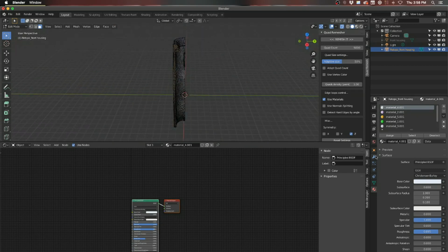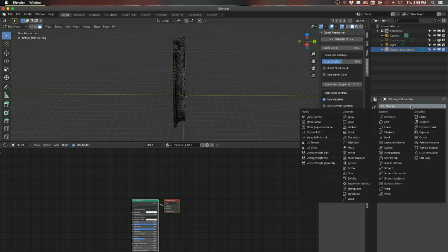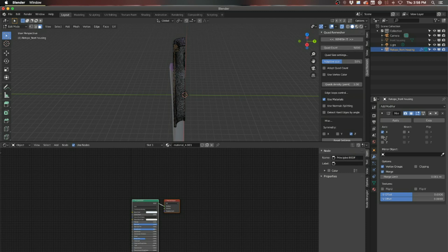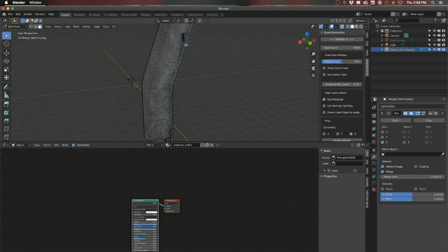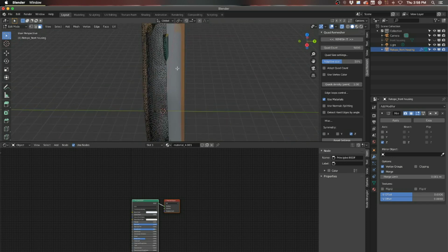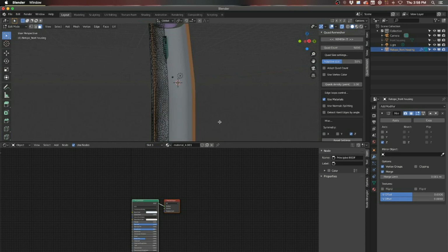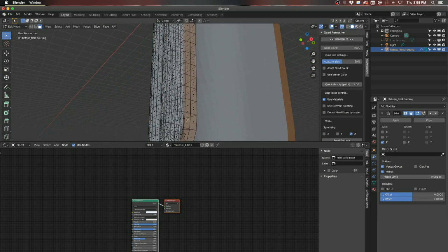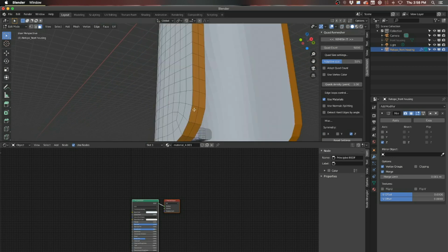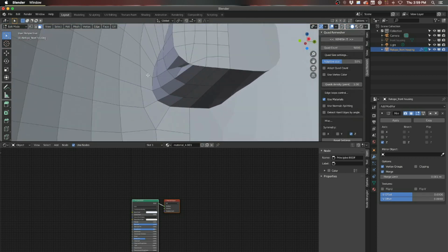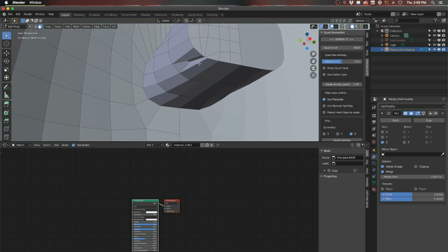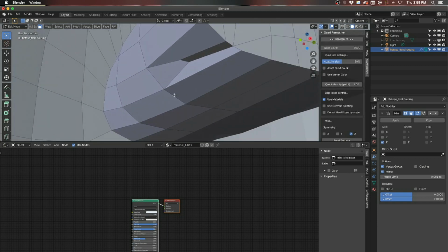And I'm going to apply in Modifiers tab over here a mirror modifier. And we want to mirror in the Z direction for some reason. So now when we edit anything over here, it's going to mirror that change on the other side. And what we'll do, turn X-ray off and just kind of cruise around the model looking for strange geometry that's a little unsightly.